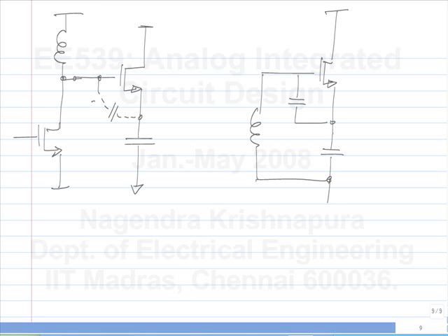Okay, this is just the signal picture. So first of all, you can add a capacitor here if you want. Anyway, the bottom line is you have some resistance, some inductance with some series resistance. And on this side, you have some capacitance with a series negative resistance. So if the negative resistance exactly cancels the positive resistance of the L, it can oscillate. Okay. Have you seen the circuit?